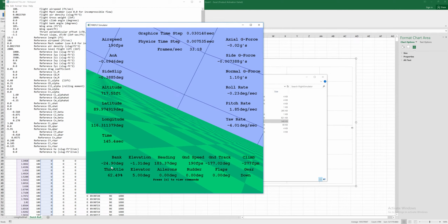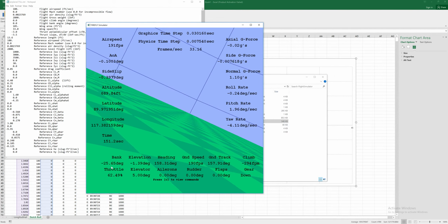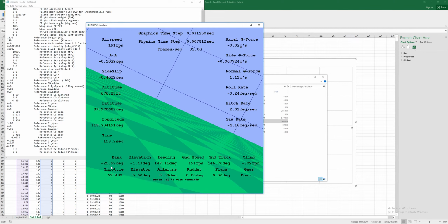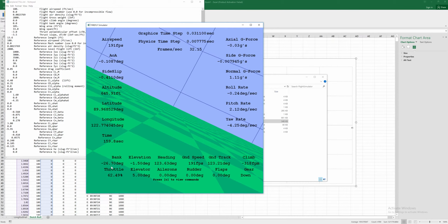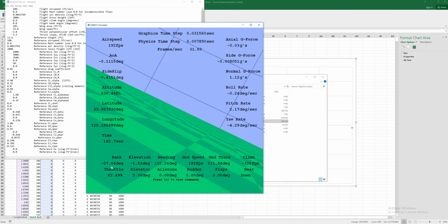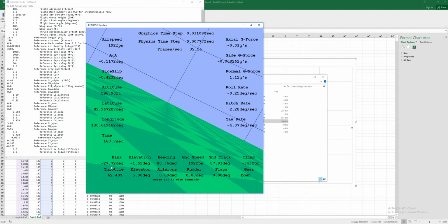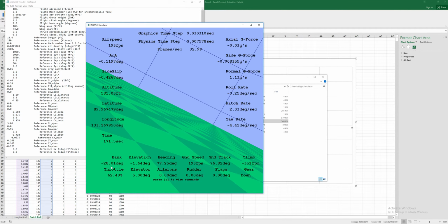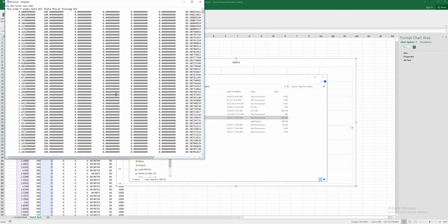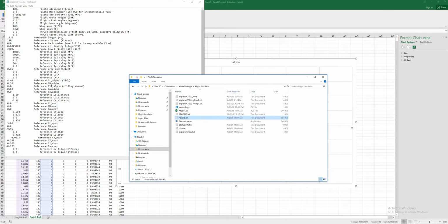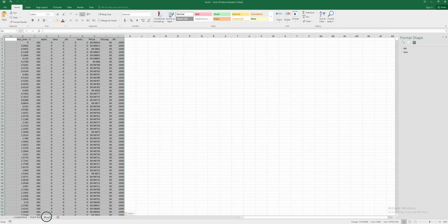Again, the spiral mode isn't terribly dangerous as long as the pilot can see what's happening out the window or has instrumentation that's telling him what's happening. It kind of feels like the alignment is out in the car on the freeway or something, and he just needs to correct for that. So it's really simple to correct. It's really only dangerous when the pilot loses a sense of what is actually going on with the aircraft because he can't feel it. Okay, so let's look at this data now. I'm going to copy that and drop it in here. And this is our divergent spiral mode.